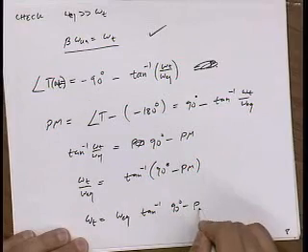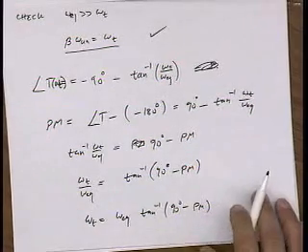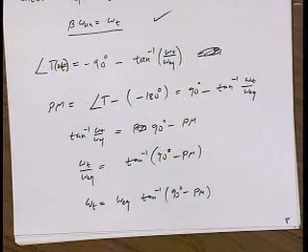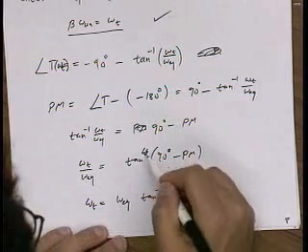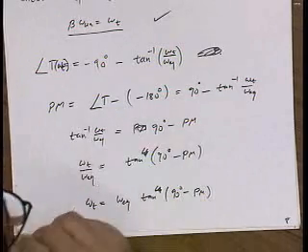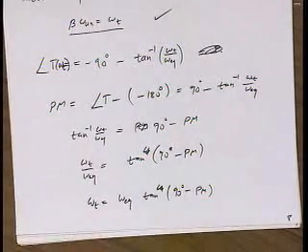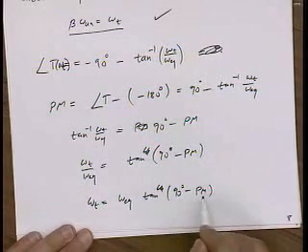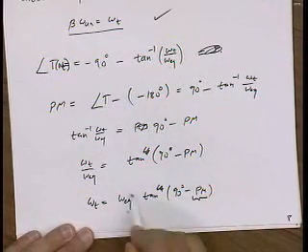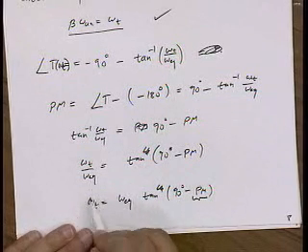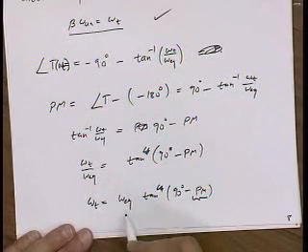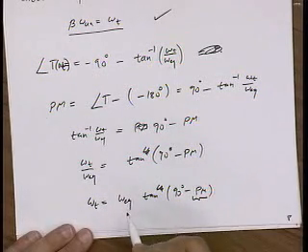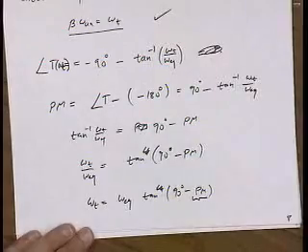this very simple result that, basically, depending on how much phase margin you want, you have to choose the unity gain frequency to be tangent of 90 minus the phase margin higher than the equivalent pole that you have. Okay?